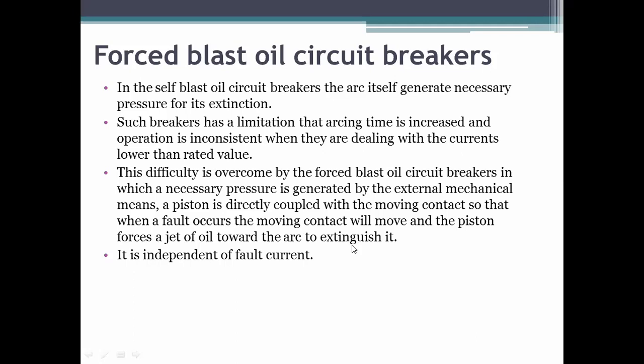So when any fault occurs, that moving contact is coupled with the piston, and when the fault occurs, that moving contact will move that piston so that the arc will be extinguished. Okay. And it is independent of the fault current.